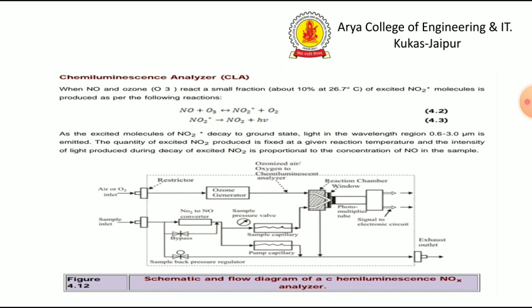The response of the instrument is linear with NO concentration. The technique is very sensitive and can detect a wide range of ppm of NOx. The output signal is proportional to the product of sample flow rate and NO concentration.